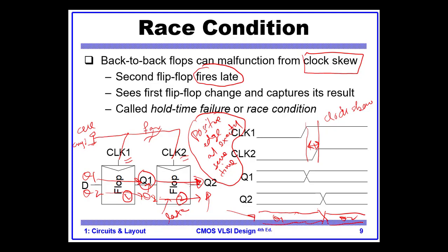So this is called hold time failure. Why hold time? Hold time because flip-flop 1 was not able to hold Q1 for enough time. Let me write this. Flip-flop 1 was not able to hold Q1 for enough time.